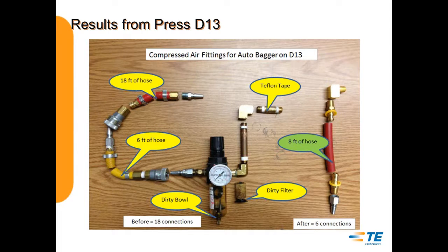Some of the other things we did from that same Kaizen event, basically when we took all that stuff off, we replumbed it. We tried to minimize the number of feet of hose. If we only needed 3 foot, we put 3 foot back in. We didn't coil it up and have the opportunity for it to get nicked or burned.